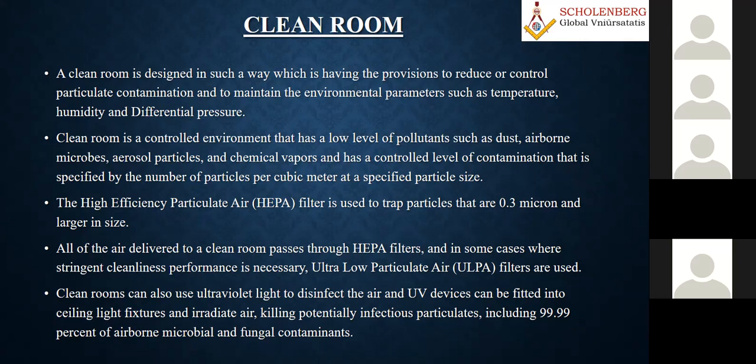So as I told you, a clean room should definitely have very low pollutants. It can be dust, airborne microbes, aerosol particles, even chemical vapors. This is what you correctly asked. For process purposes, many people use different kinds of equipment, and that equipment will definitely create formaldehyde and many other things. In the laboratory, they may be using so many chemicals, so they will definitely produce so much vapor. That all has to be controlled in various stages. So that is basically the main importance of the clean room.